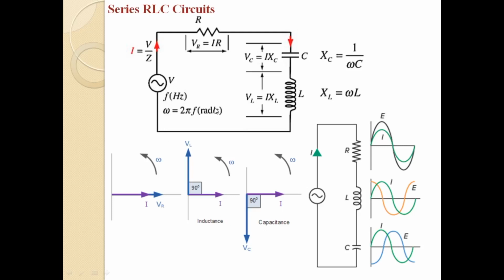In order to recall, the phasor relation between the current through different elements and the voltage across them is reproduced here. Here you can see the phasor relation between the voltage and current in the case of a pure resistor, a pure inductor and a capacitor. In all these cases, we have taken the current through that element as a reference, so the phasor corresponding to the current is drawn along the positive direction of the x-axis, that is the reference direction.